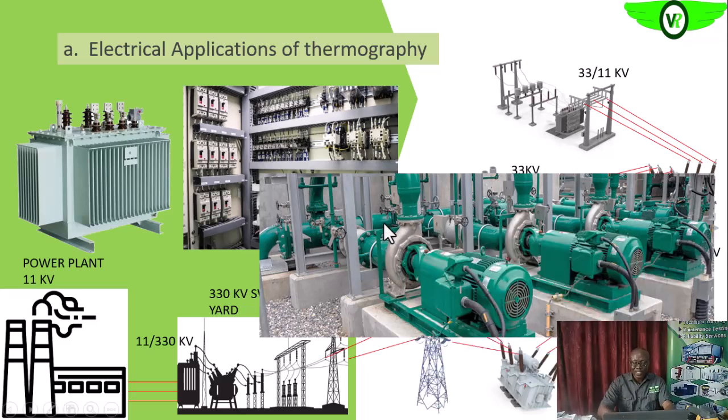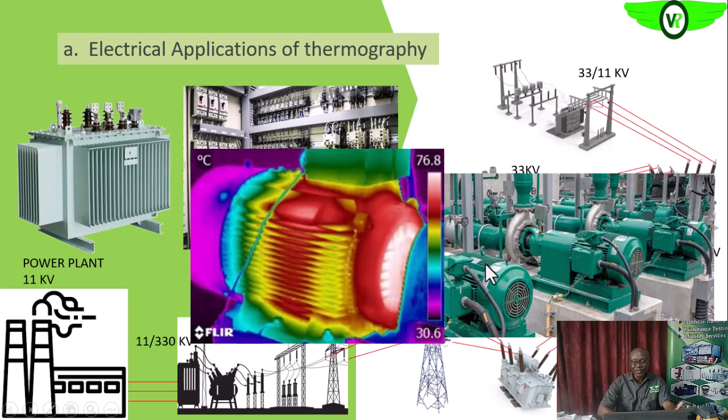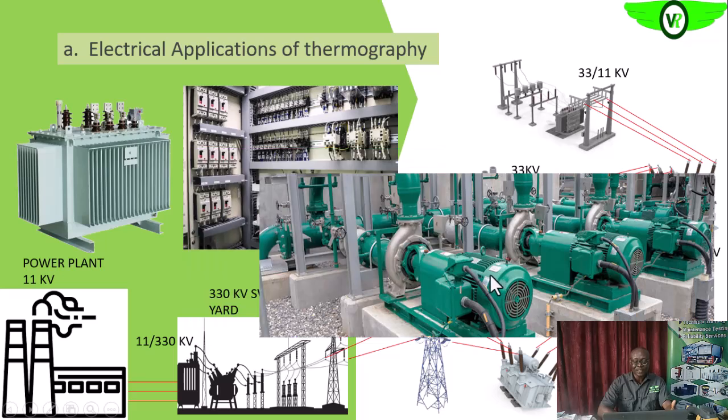Then on mechanical equipment, as we said earlier, we will see the thermogram on a normal working motor. The motor also has winding, and there is an insulation between the winding and the yoke that is coupled to this frame internally. So the winding transmits the heat that will be generated on it because of the current that is flowing through the windings during normal operations. So that heat that is generated within the winding will be transmitted or transferred to this body. Okay, so you see the heat coming out. As we will also see later, the cooling effect of this fan, you also see it.